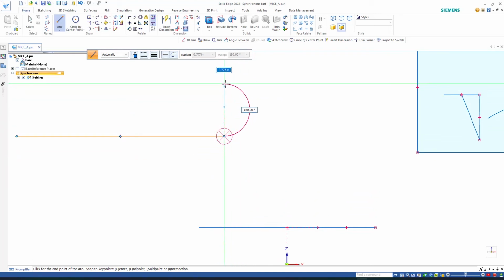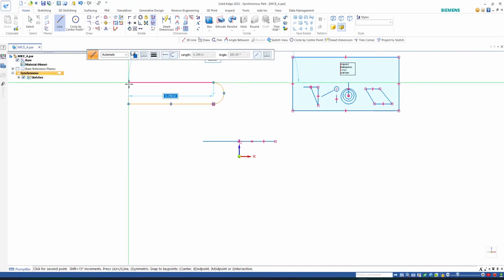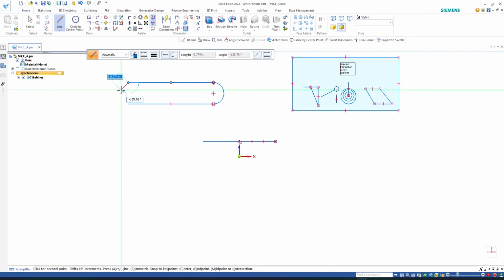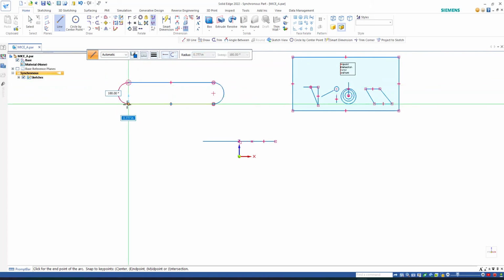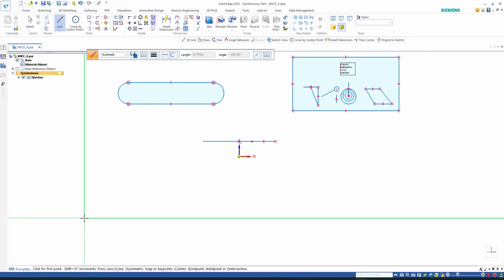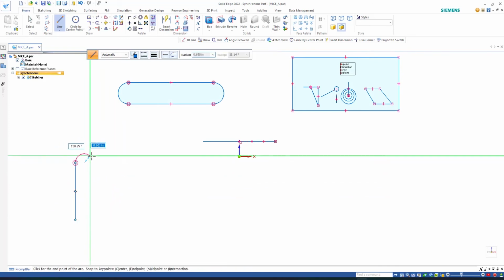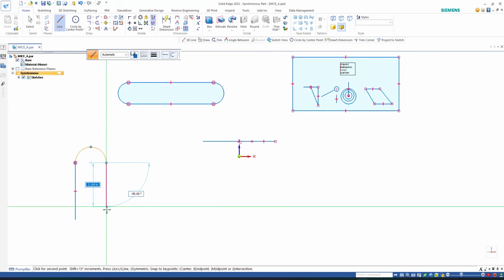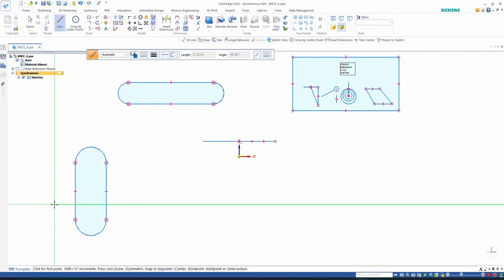All right. So I'm going to left click again, continue on. See, it's left with my line here. And then do the same thing, but this time I'm going to hit the A for arc, and you can see that quickly I could create an arc. So I'm going to do both now. I'm going to do something like this, hit the A on my keyboard, continue on with my line, A, and you're done. See how quickly you can do something like that.